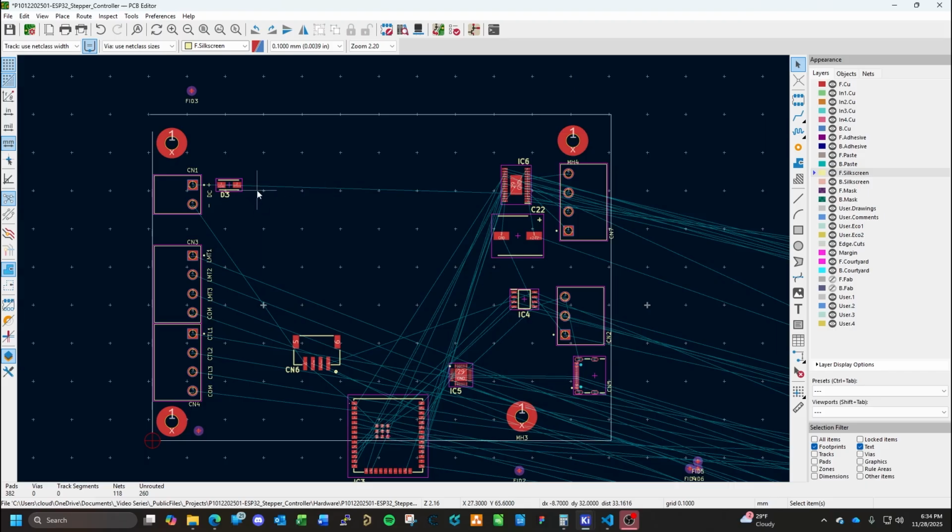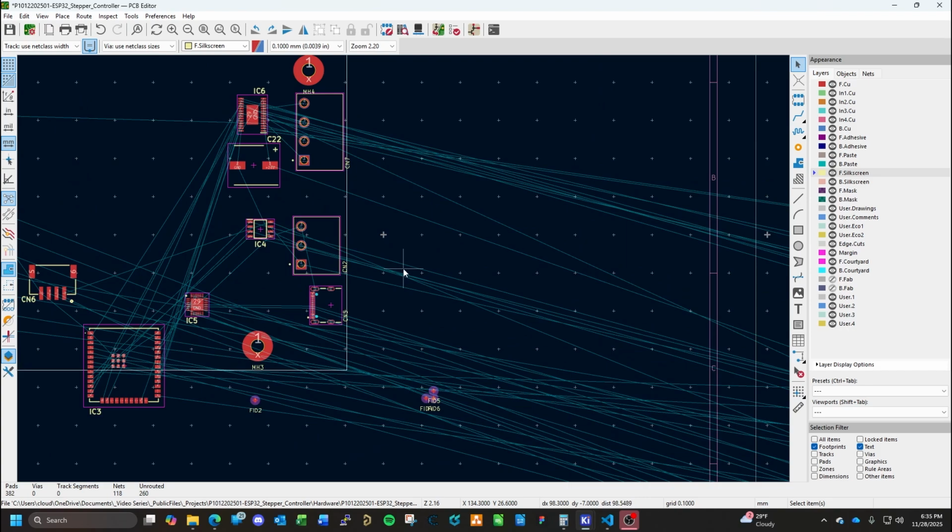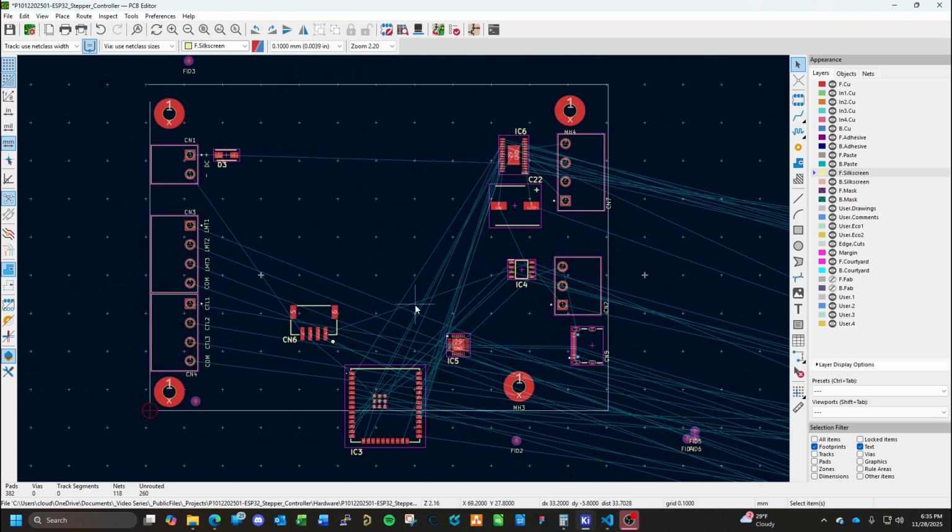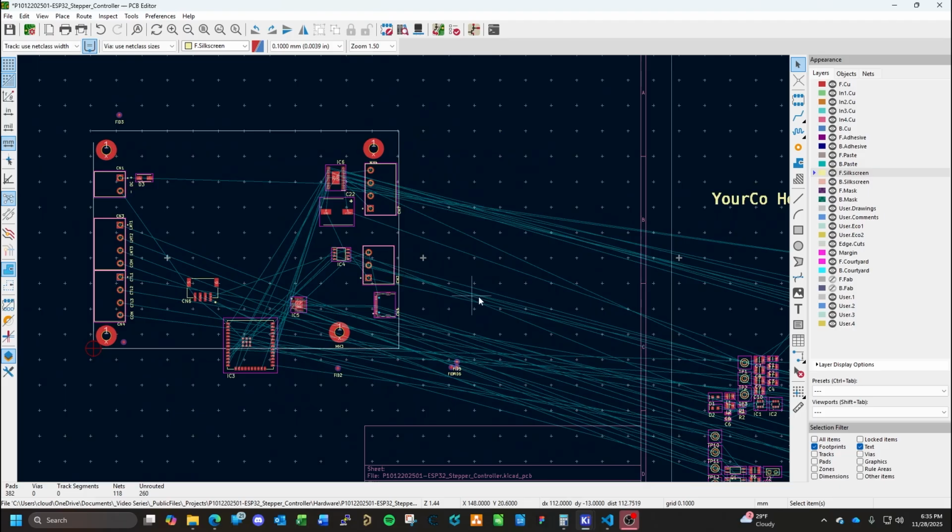And there. I figure the 24 volt, like a major power rail, can kind of come up here. Since we're doing this here, we should put the 3v3 and the 5 volt power supply in here. So the 3.3 volt power supply is going to get a dedicated power rail, or an internal plane. So one's going to be 3.3 volt, the other one's going to be ground. But the 5 volt will just be traces to go wherever we need them, because right now it's just going to power the fan.